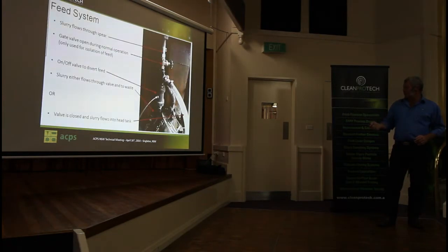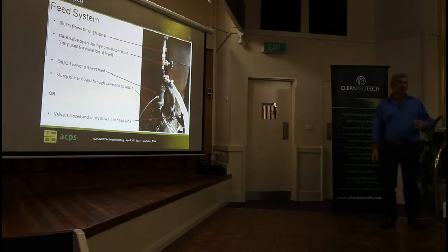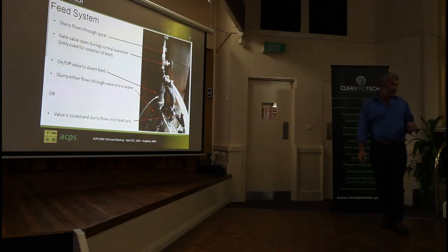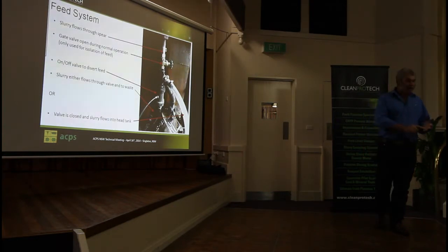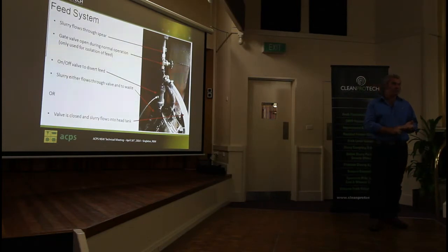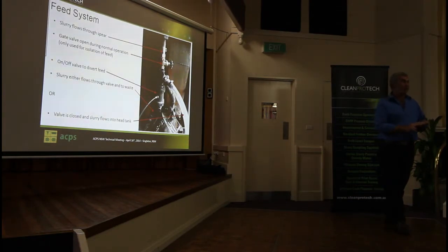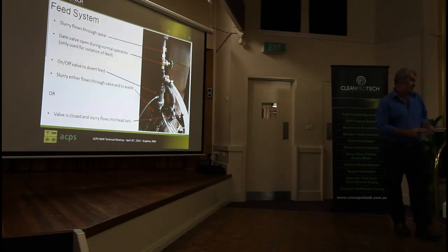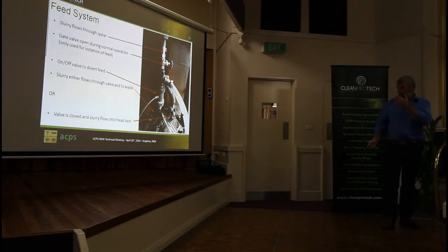From the feed system, which has the top of our deaeration tank there, deaeration was also a major issue that we had to face with such a system. Any instrument measuring slurry density, even conductivity, solids concentration, any air in the stream will hammer it. We spent a lot of time getting that deaeration system just right. And with the slurry density measurement, we could prove it was working very well quite simply by shutting the bottom valve and seeing if the slurry density went up over time, if air was escaping. And it never did, once we got the system right.